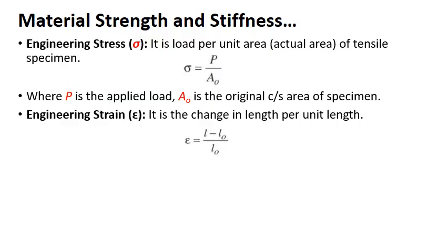For us to apply the definition of engineering stress, all the imaginary fibers of the circular rod must be pulled equally. That is not possible in the shoulder region. So we locate L0 somewhere in the central portion of the specimen, where all the fibers will be subjected to uniform deformation.